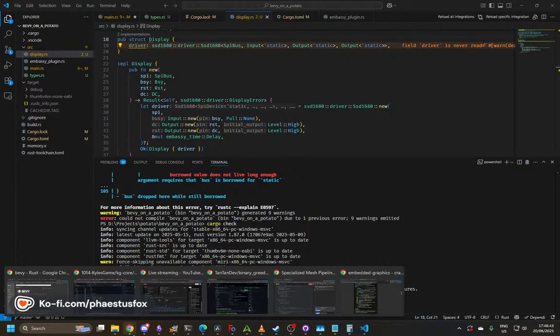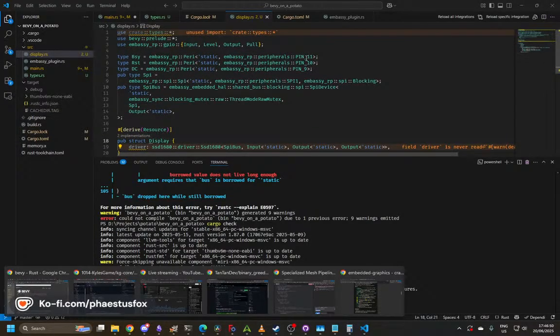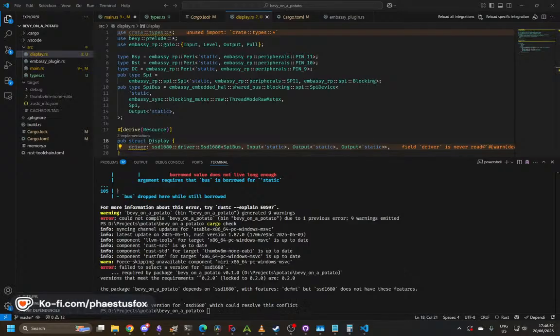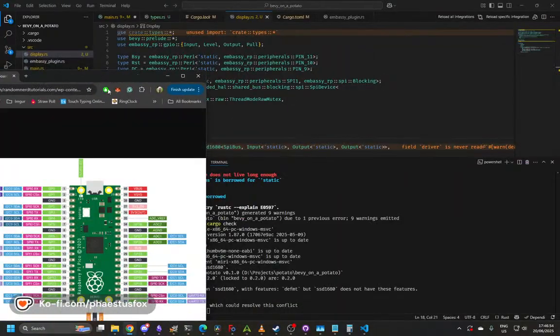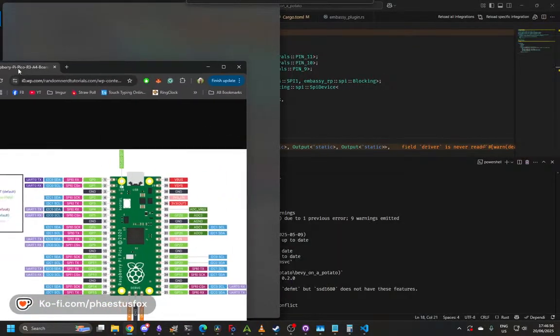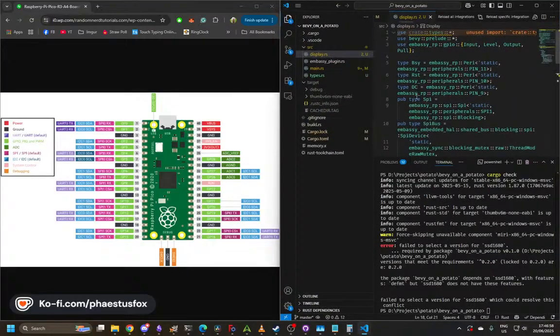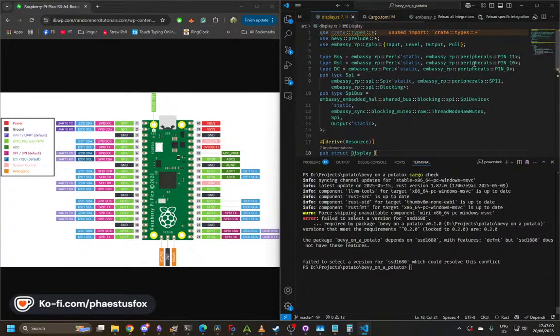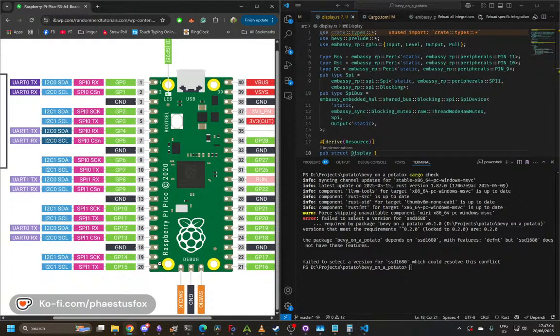Okay, so my busy signal. Busy. And busy is, what pin is busy? Busy is pin 11. And we go to our diagram over here. We'll put something on screen so you guys can see at least something more than just silence. Silence, nothingness. Okay, so busy, pin 11. Pin 11 is 2, 4, 6 from the bottom.